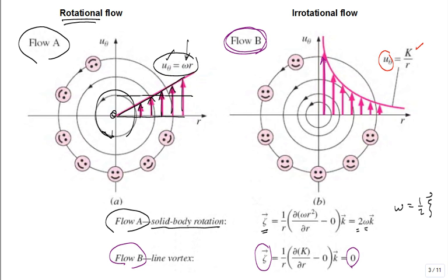So if the vorticity is 0, it's not rotating. And the way you can visualize it is drop a coin or something that's going to float, a little marker. And the marker has some north, south, east, west, and then see if the north always points north as it's flowing in that flow field. Or in this example, they drop a smiley face, and the smiley face is looking straight at you. But in this flow field, as the smiley face is moving, the face actually rotates. So that's a rotational flow field.